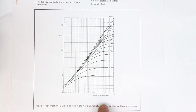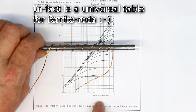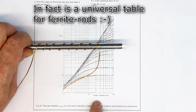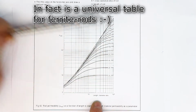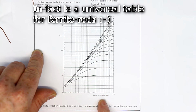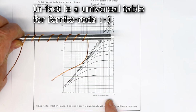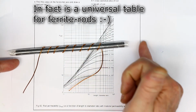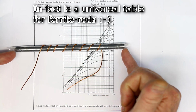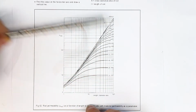Here you can see a graph from exactly this material from Ferroxcube, 4B1 or 4B2. You first need the length to diameter ratio, which in this case is around 18, the ratio between the length of the rod and the diameter of the rod.